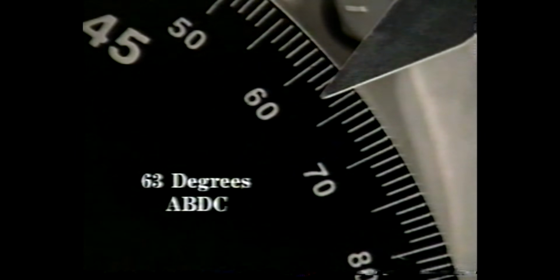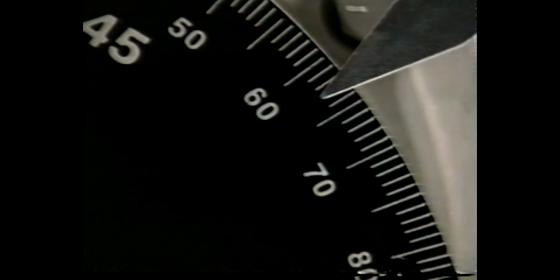center. It is the separation between the closing of our front intake valve and top dead center that determines where our particular camshaft will develop power in the engine's RPM range. In our case, the closing of the intake valve is at 117 degrees before top dead center. To arrive at this value, we first shift the reference for the valve's closing point from bottom dead center to top dead center by adding 180 degrees.